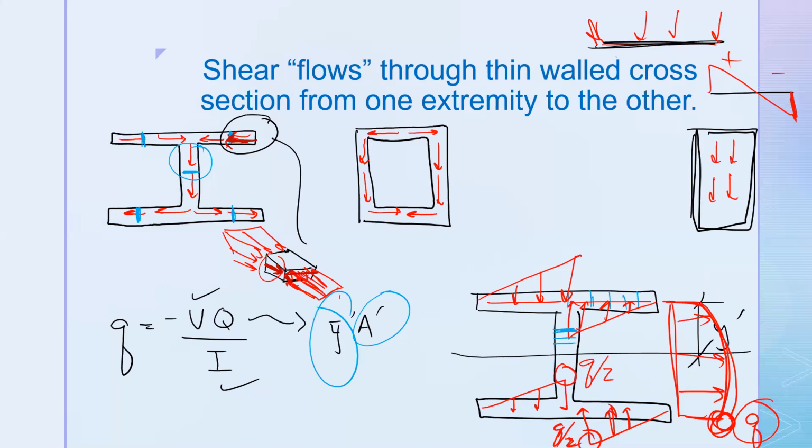All of our calculations when we do this are with respect to the center line. What I mean by that is the shear flow is passing through the center of our cross section. So this, for example, is our wall. This then is our flange, and you can see that there's a little bit of overlap there in that corner, and that overlap is equivalent to the area that we're missing, right?